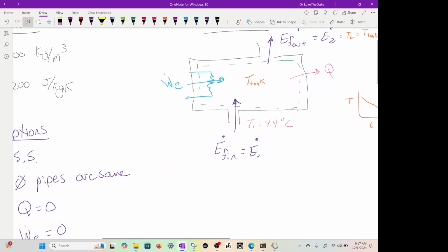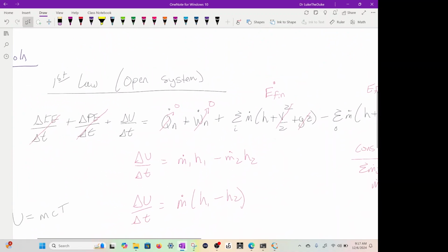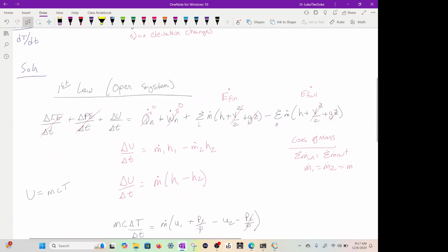So what we did, going over here, we used the first law, and we neglected kinetic and potential energy of the system. Just a side note, you use these two in physics class with a ball, and you neglect this one because the ball doesn't change temperature. But in thermo, temperature changes, so you use this pretty much most of the time.